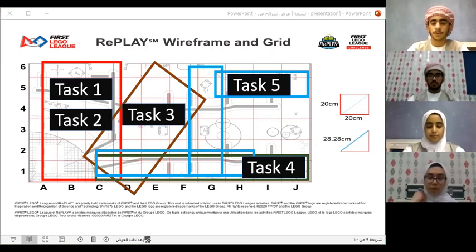We have programmed the robot to return to the home area when each mission is finished to avoid deducting accuracy points. Through our strategies, the robot's behavior on the pitch is guided using sensors such as color, light, rotation sensor, and gyro sensor, as well as alignment by following the wall, alignment on the wall, as well as alignment at the base of the launch to get a good start and carry out the tasks with accuracy and smoothly. To perform tasks, there are a number of steps in programming.